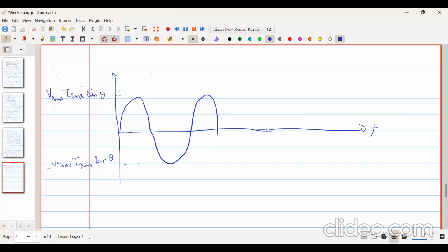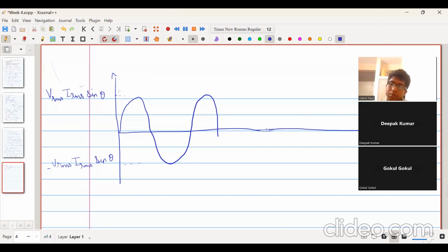But when there's reactive power in the circuit, the amount of current flowing in the circuit will increase, and when the current increases, there are more losses. That's why it is preferred to decrease the reactive power flowing in the power system. It is a very advanced concept. It's not that reactive power is bad. Some amount of reactive power is necessary to set up the flux in the transformer or the induction motor. That time you need reactive power. But it will be lossy in the cables and other parts. That's why they have power factor correction circuits, so they try to reduce the reactive power being used.